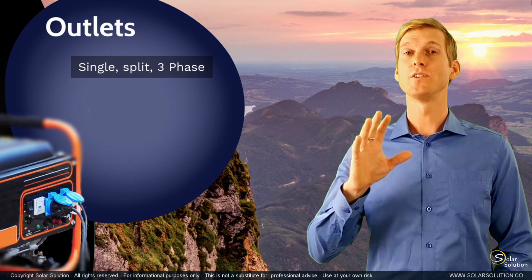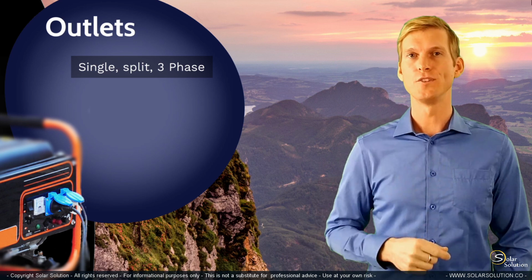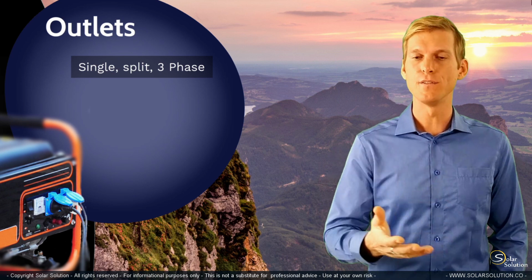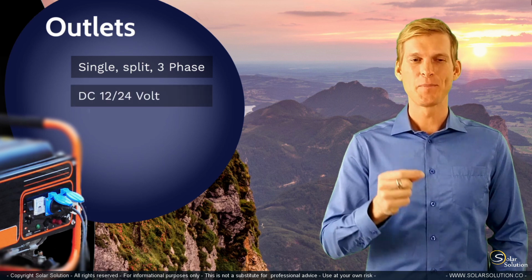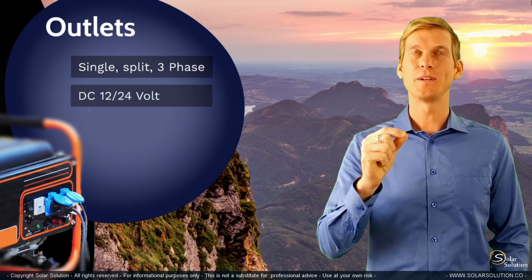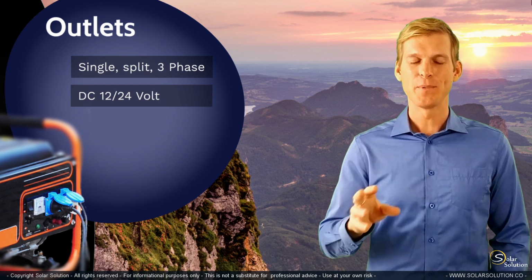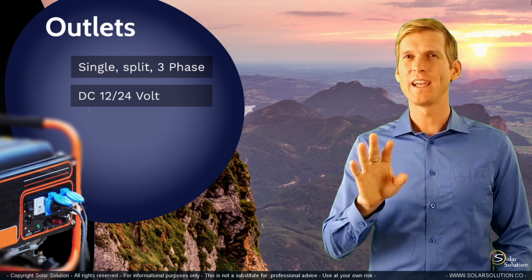But there's one thing which is often overlooked, which is the DC, the diode current capacity of your generator. Most standard or advanced generators have the ability for you to connect a battery straight to your generator. But often people get a bit disappointed because they think they can charge a large battery bank, so double check, because most standard generators can charge with around 8 amps.